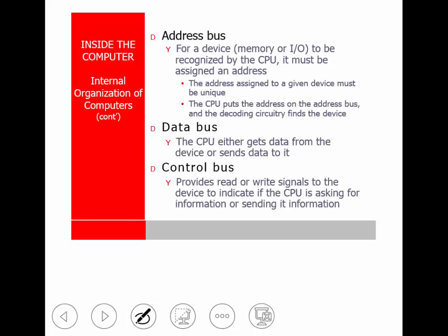You look at it as the stoplights and the signals in between. You tell devices to stop, wait until I'm done with the bus, and then you can have it. Because the address bus, let me just point out, with few exceptions, the only one that writes the address bus is the microprocessor. He controls the show. He's the only one that can write to the address bus.